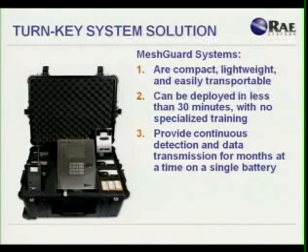It provides continuous detection and data transmission on a single battery for months at a time. This is really why wireless systems are relatively new to the industry. Why hasn't this been done before? It really has to do with the technology. In today's world, we have batteries and very low-powered radios and sensors that can be powered for 6 months at a time. Previously, with our portable instruments, or anybody's portable instruments, the battery life was somewhere between 6 hours and 24 hours. That really doesn't work if you need to do true 24/7 monitoring. With low-powered radios and low-powered sensors, you can really do a 24/7 deployment without worrying about it.